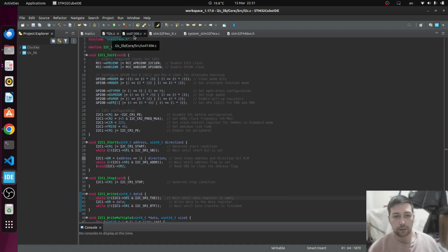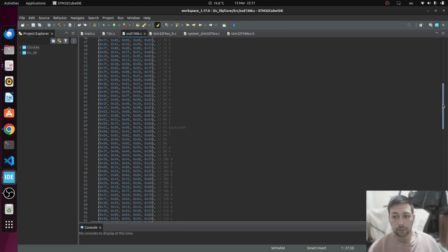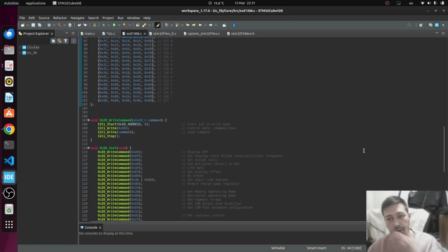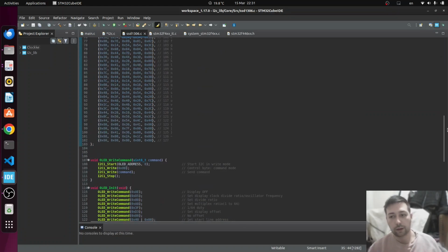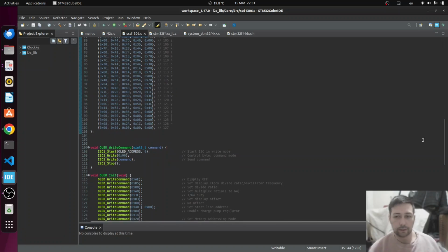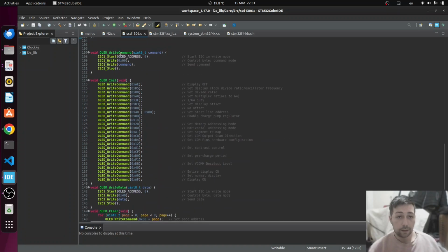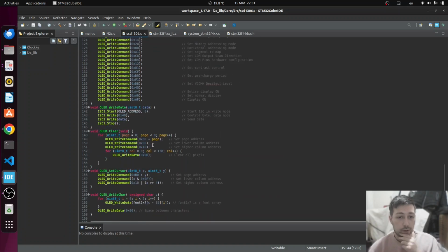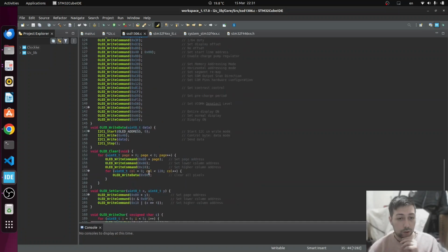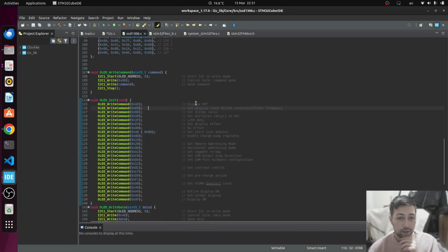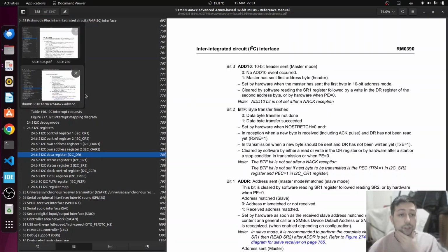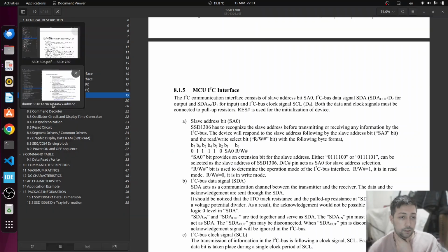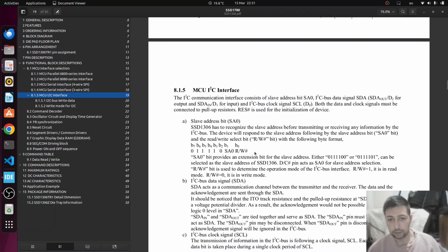So the I2C library is going to be like that. And for the OLED screen, I will just add the font. Normally they put it in another .h file, but I just put it there. Doesn't matter. So this is for the OLED screen. I also wrote that on my own. For these things like display off, you have to check the datasheet of the OLED screen, the SSD. This one, yeah, this is the right one.